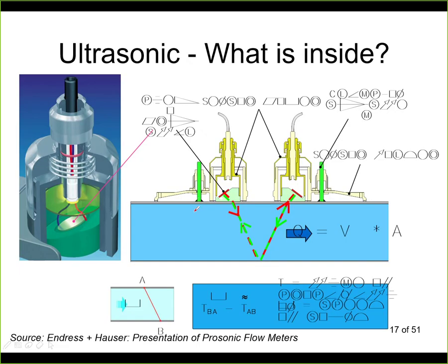This is how it looks like. So this is the piezoelectric transducer. I see it's some problem with the fonts on my computer. Anyway, this is the piezoelectric transducer. Here this generates the ultrasonic signal. Now through this wedge it gets transferred into the wall, and from the wall into the liquid like that. Here on the second wall it gets reflected, and it is received by this second transducer.